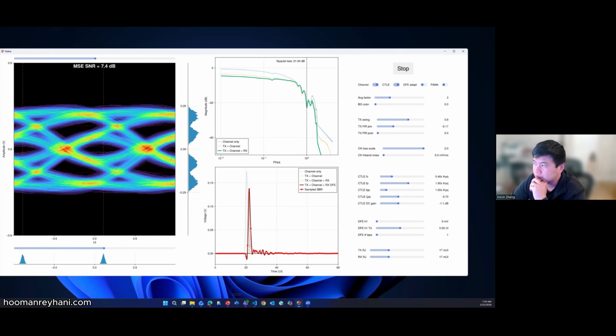But what's the problem? The problem is, let's say I start to add system noise, right? Let's say I start to add system noise. The eye, you can see, is effectively closed again because you get this noise in the middle. You can make a mistake here, right? You can achieve a similar effect if your TX jitter started to increase, right? That can be visually seen on the eye diagram. Or you can say my sampling distribution got worse, right? If you increase that, even though the incoming eye diagram does not change, this spread over here is going to change.